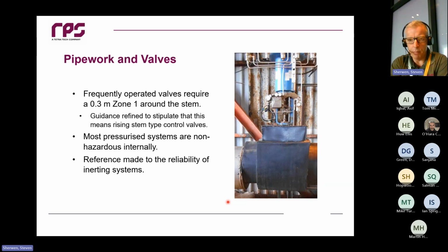It basically says that what we mean by a frequently used valve is a rising stem control valve. It's not an isolation valve that's opened or closed once a week or even once a day. It's a valve that's constantly cycling. So if you've got a pressure control valve, a level control valve, or a flow control valve that's always moving to maintain a set point, that's what we mean by a frequently operated valve. The packing in that valve becomes pretty similar to the packing you get on a reciprocating pump or a compressor.